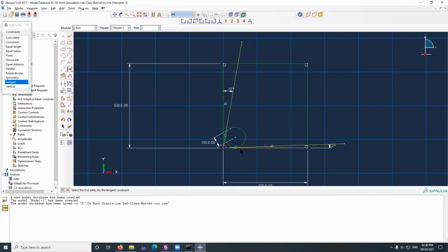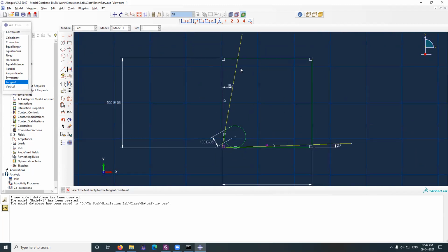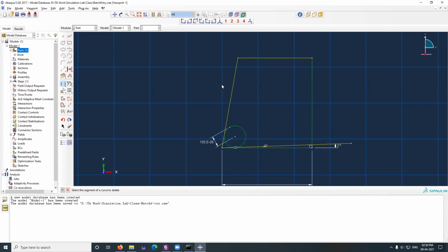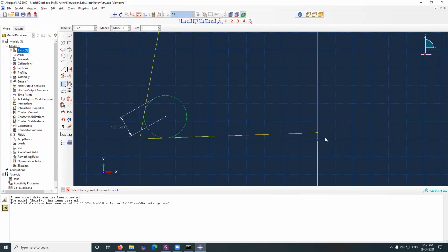So all I have to do is trimming of unnecessary parts. So my part is this one. It goes like this, goes edge radius, then it goes like this and goes back like this. So I will do the trimming part. Okay. So this is the trimming part, auto trim. You click this one and go over here, it will highlight the unwanted one. So these are unwanted. So I'm removing this, I'm removing this. Zoom it, this is also unwanted, this is also unwanted.